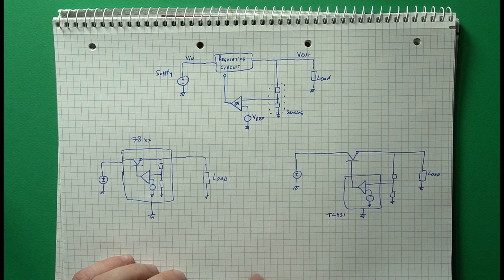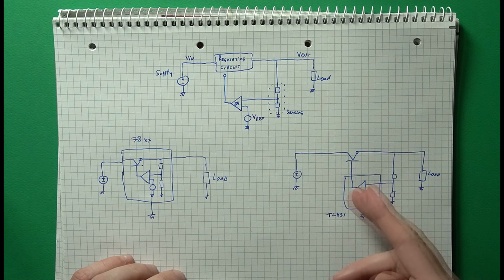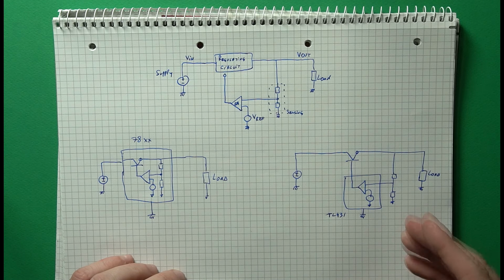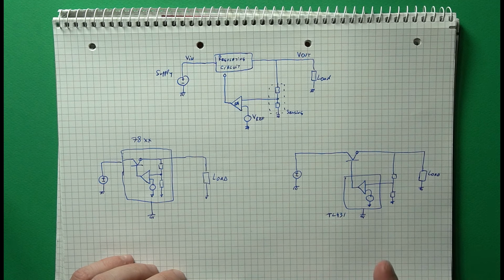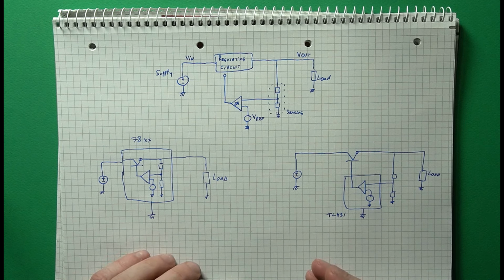However, other circuits that offer variable outputs, like a power supply built around the TL431, have the voltage reference and comparator integrated, and then the sensing resistors are placed outside, so the user can put whatever values they want here. Now, a power supply may be split into more bits than this, but these are the two most common approaches when analog control is implemented. Specifically, the feedback resistors may or may not be integrated.